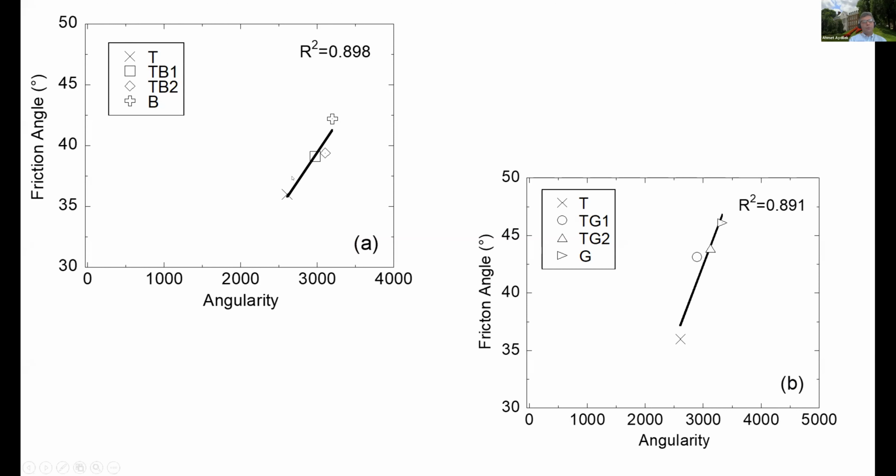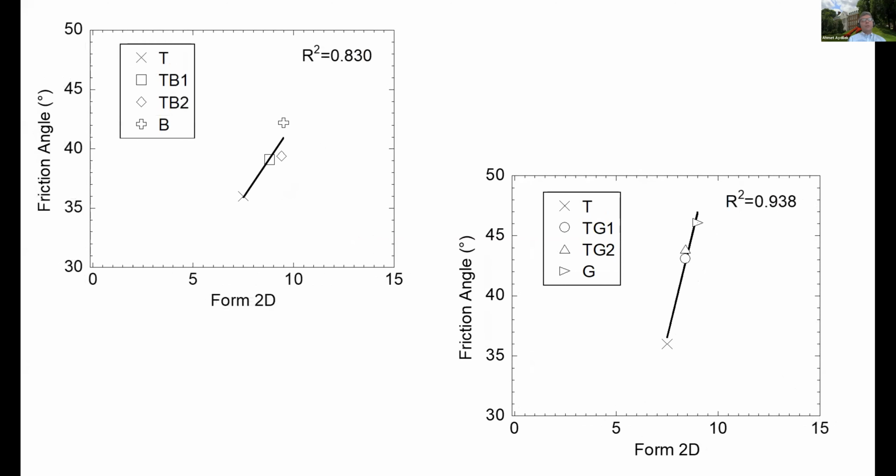In this case we were right, and it was obvious that there were fibrous elements inside the blend that were increasing the friction angle, and the same is true for the leaf compost. And if you look at, for instance, elongation, you can see the same things. You have more elongated, and as you have seen in the earlier slide, more angular particles with the inclusion of the compost, which basically tells us that this was the main reason for the increased friction angle.